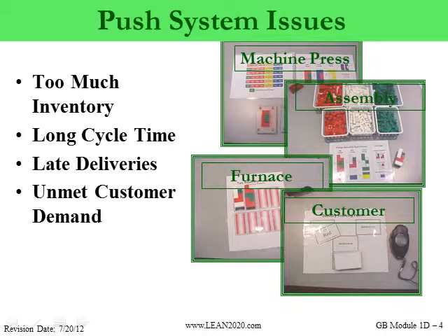What do we have to do? We've got to throttle back that photo imaging department somehow. Unfortunately, what happens is because you have such a large backlog of panels, the order of processing starts to become jeopardized. So you have a hot job that comes out of the photo imaging department that is not sitting in line. It's jumping over all of those other panels that are sitting there. So some of the product that may be in the plating department's backlog may actually be sitting there for more than a week's time, maybe several weeks or even a month, because of the order of processing.